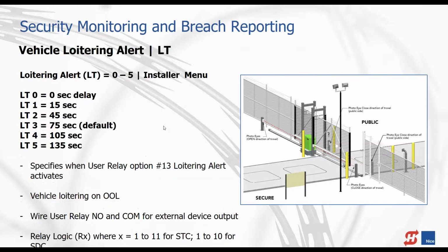So Daniel. Yes. Why would a gate be open too long? What condition would cause that to happen? Well, maybe something is on one of your peripheral devices, maybe it's on a loop, or maybe the gate operator is having a problem. There's some hardware issue, or there's a roller that's stuck or something, so it can't close that gate. There's multiple reasons, but it's good for you to be able to know that that's happening, right?